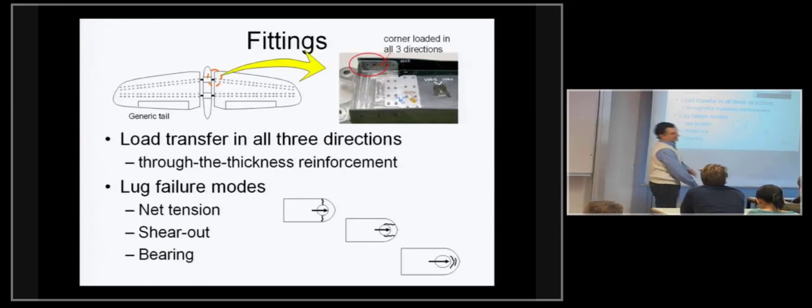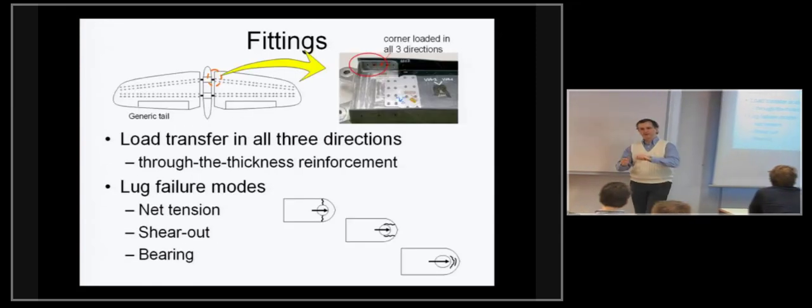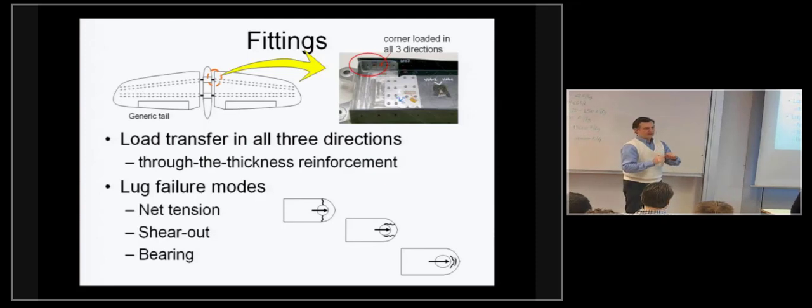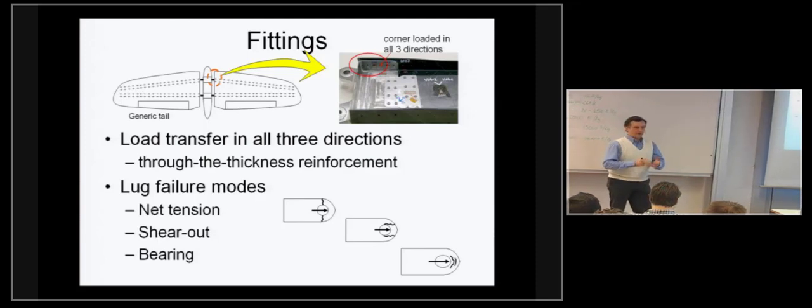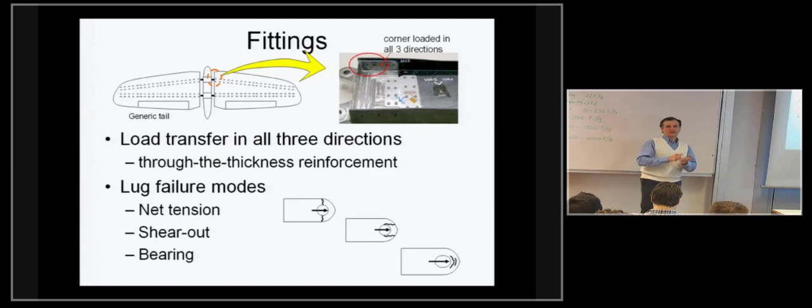Fittings. Fittings are these small gizmos that connect different parts. Therefore, almost by definition or as a rule, in many cases, they will carry load in three directions. As soon as you have load in a structure that's in more than two directions, that means there will be some part of the structure that sees out-of-plane loads.